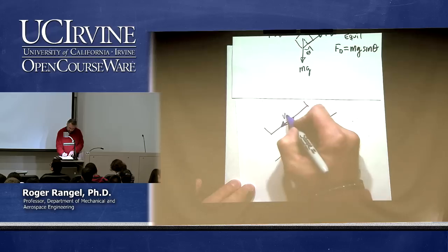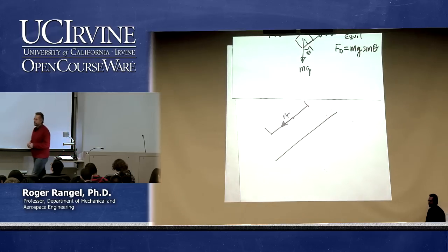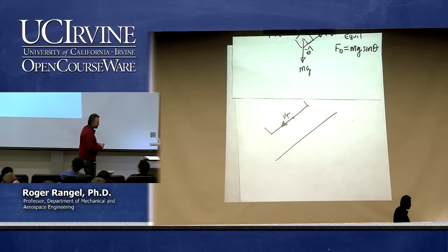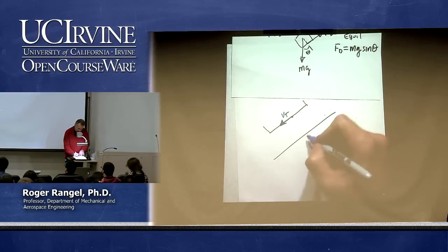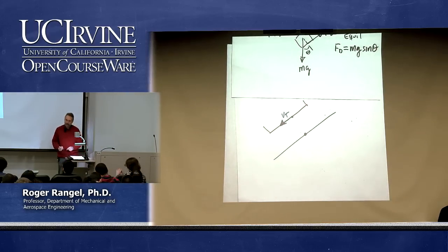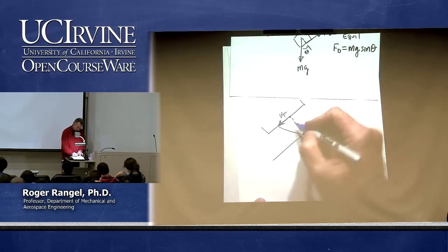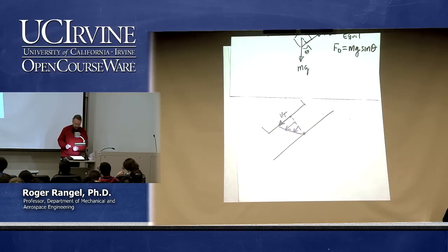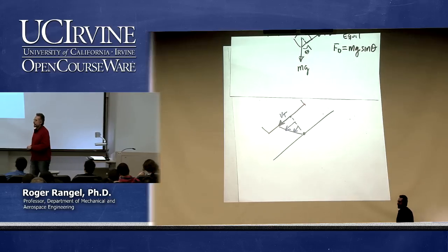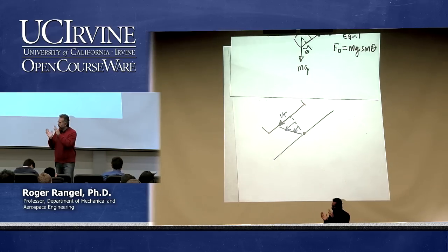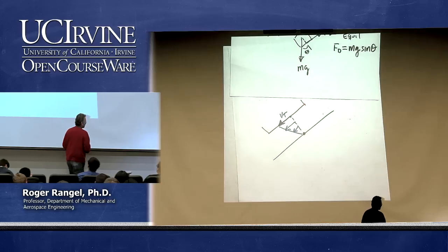So this is Vt. And what happens to the fluid velocity as I go into that film? It'll have to be 0 here because of no slip. So it has to look like this. Hey, that's a Couette flow. There's a Couette flow under the block.